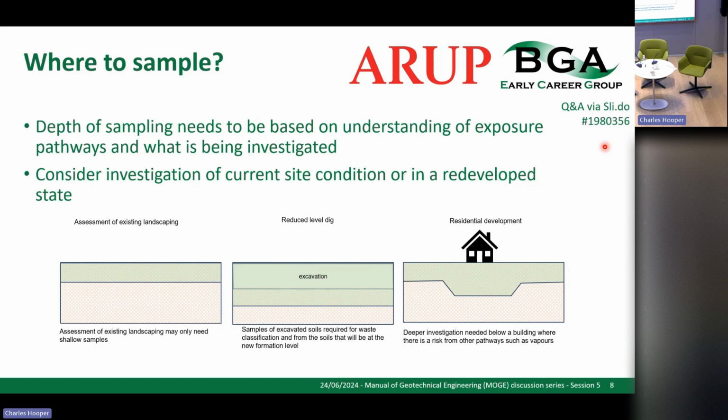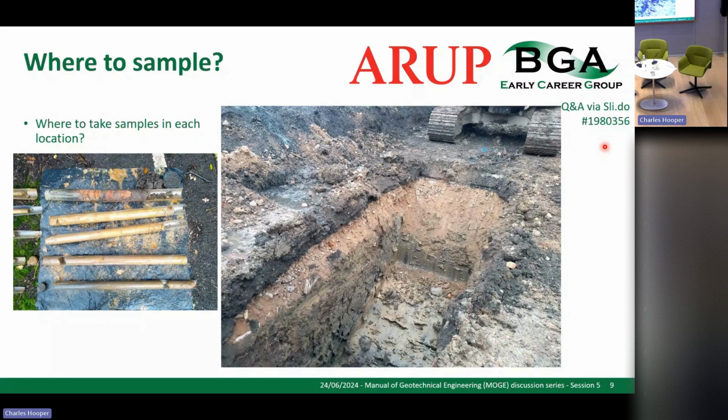So for that one, around the building you could probably do a shallow investigation if you want to, but within the building you've suddenly got a deeper area that you have to look at to make sure you're covering all the assessment. And that's why it's so important to look at how much you need to do beforehand, before you get to site. And so it's really important that the CSM, the conceptual site model, is thoroughly developed. And even once we've decided how deep we're going to go, you then get onto the stage of deciding what you're actually going to sample.